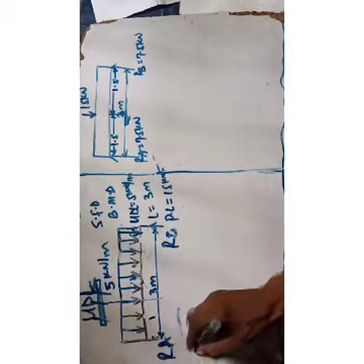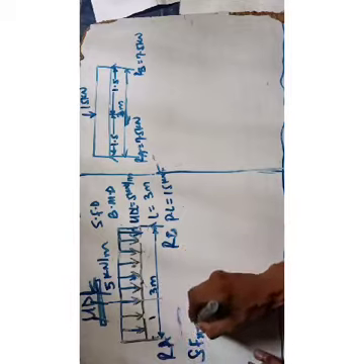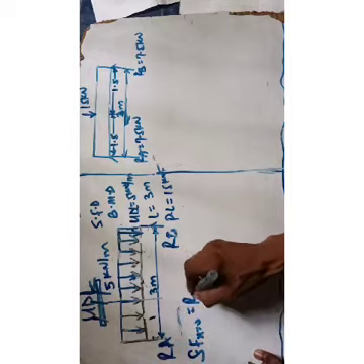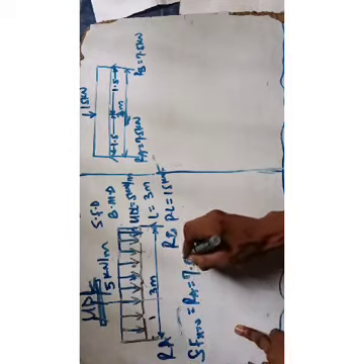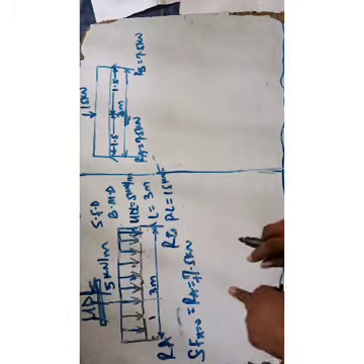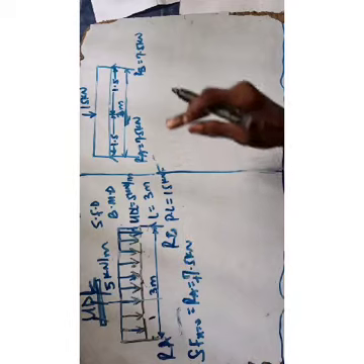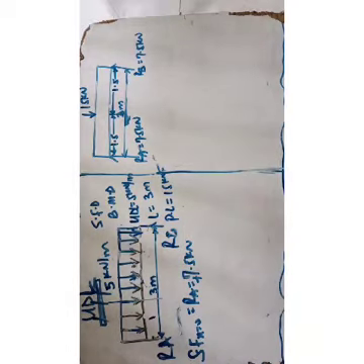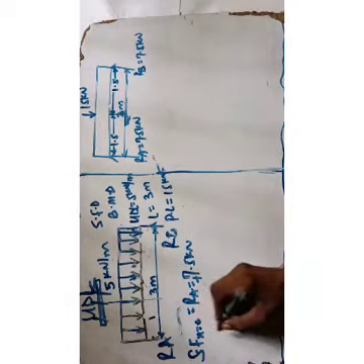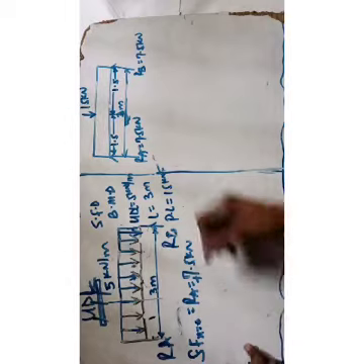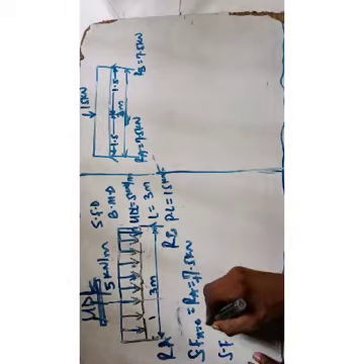Ra. So shear force when x equals 0 is equal to your Ra, and that becomes plus 7.5 kilonewton. Now, next thing you do is shear force when your x equals 1. So it's very important you split it.